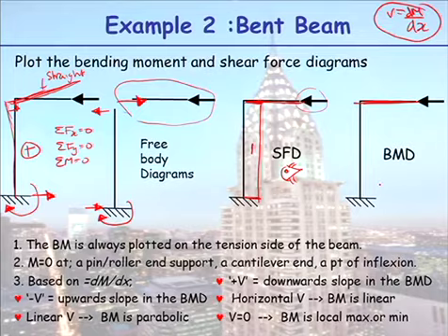According to my shear force diagram, it's a negative shear force diagram. Which way is my force going? It's a negative shear force diagram, so that's an upward slope. So my bending moment diagram will look like that. Does that make sense? Then you go and check it. I got bending on that side. Yes, that's the side in tension. My horizontal leg is straight. Yes, there's no bending moment in it.